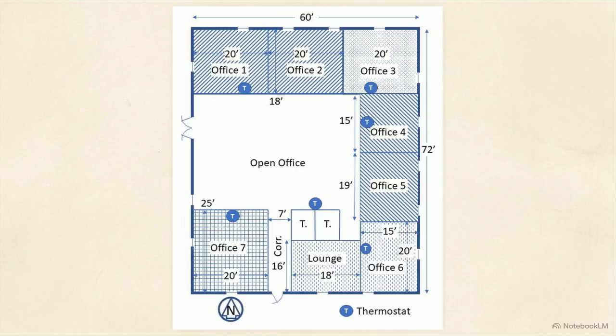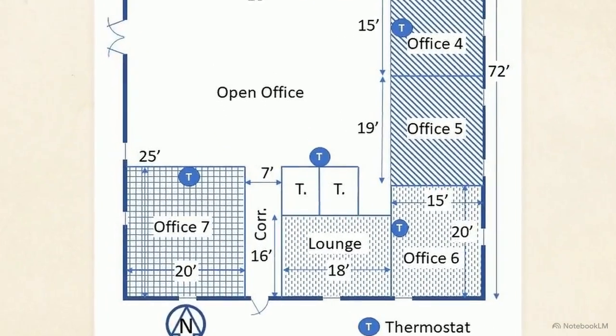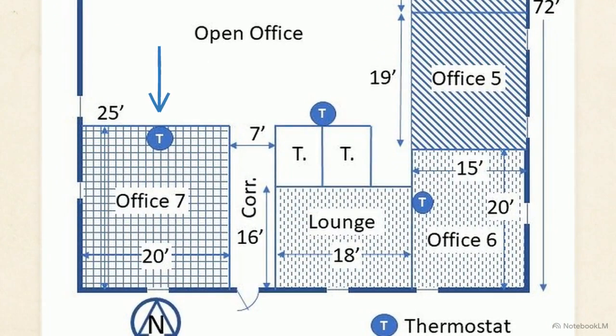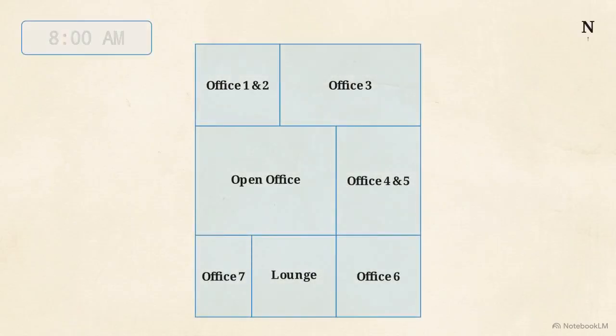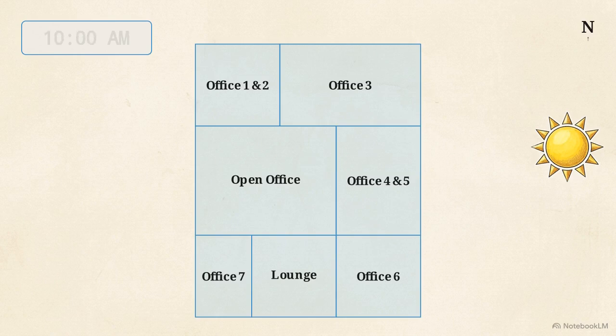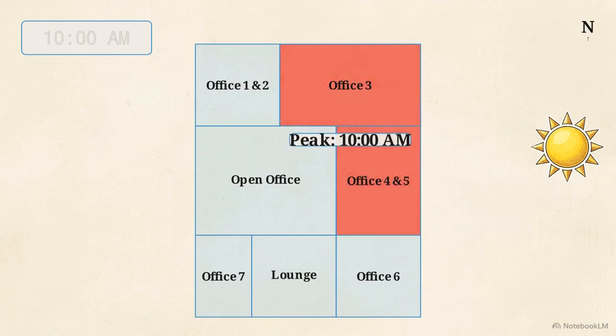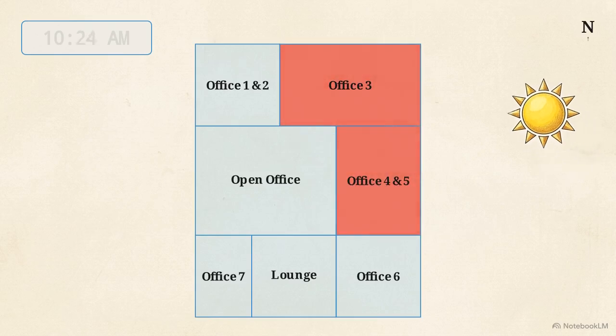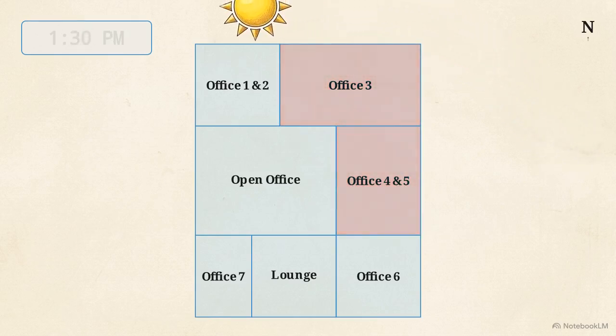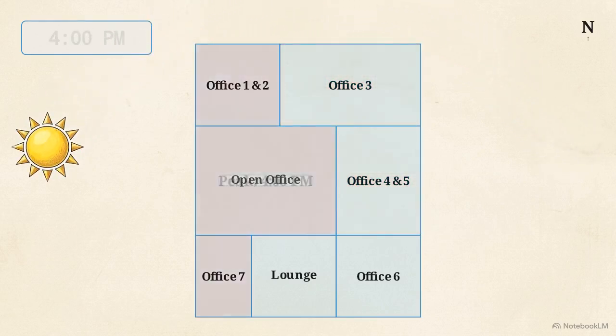Most commercial buildings require more than one single monolithic thermal zone to maintain occupant comfort. Instead, a floor plate is divided into distinct thermal zones, each monitored by an independent thermostat. This introduces time-domain complexity. Due to the sun's movement, perimeters do not gain heat uniformly. Eastern zones absorb intense morning radiation, peaking by 10 a.m. As the sun travels, the burden shifts, forcing western zones to peak in late afternoon.